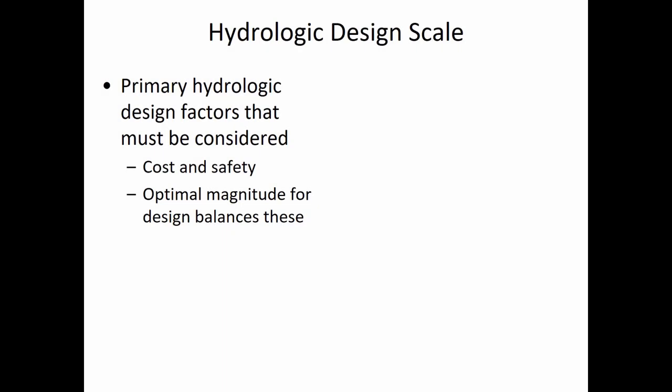The first thing that we'll talk about is expanding our view of storm return period. In a lot of the analysis hydrologists do for engineering design, the scale is relatively short. You're looking at maybe sizing a ditch for the 2-year storm, or sizing the inlets on an arterial road for the 10-year storm. At the high end, the drainage system for an interstate freeway is supposed to be designed so that there isn't standing water during the 100-year storm.